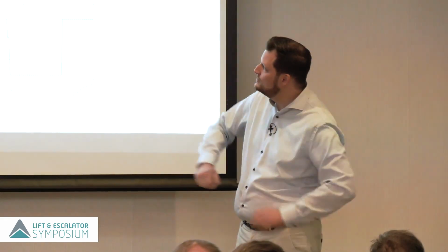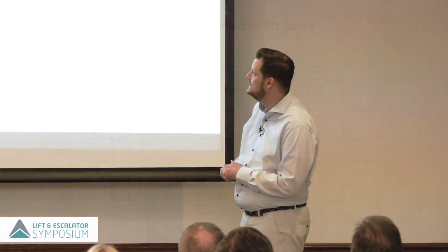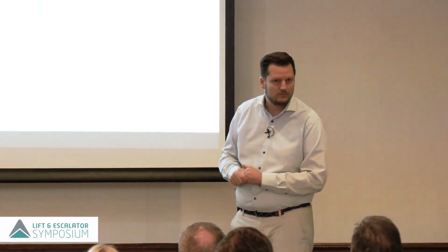So what you can actually do is, if you take pressure, from barometric pressure, you can actually already get a very good reading on where a lift cabin is relative to the floor. We've been able to get it purely by these readings down to a 20 centimeter accuracy just by barometric pressure, actually in our solution. But it's still not good enough from our point of view.